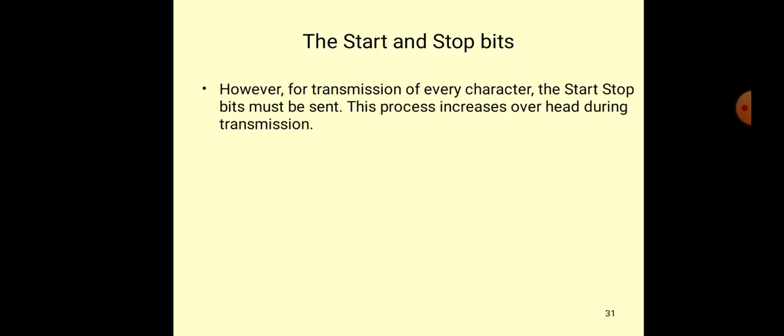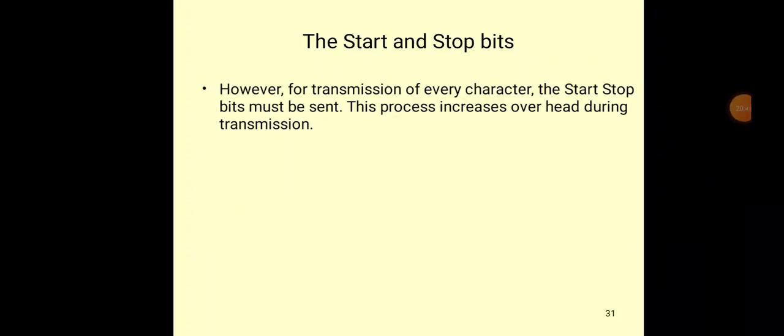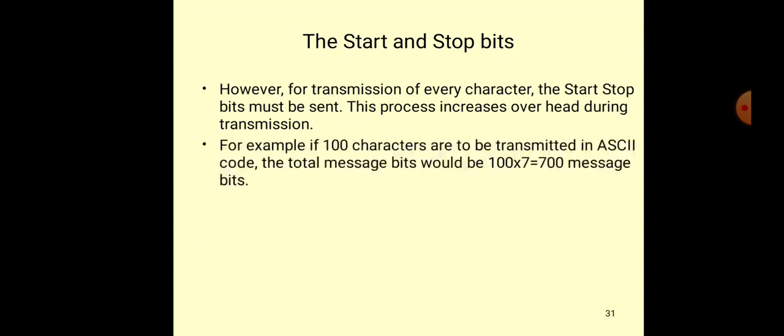Generally, in serial transmission, one bit follows another, so we need only one communication channel. The transmitter has a parallel to serial converter, the channel, and the receiver has a serial to parallel converter. The advantage of serial transmission over parallel transmission is that only one communication channel is required, so the cost will be low. Serial transmission is classified into two types: synchronous transmission and asynchronous transmission. We have already gone through what is meant by synchronous type, and we'll revise it once again.